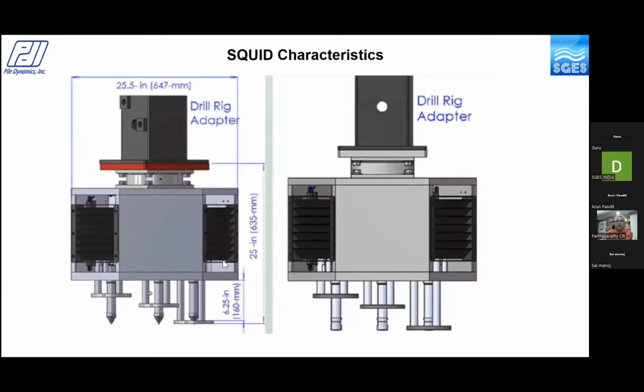Okay, so SQUID is a shaft quantitative inspection device. This estimates the thickness of contamination in the pile borehole, particularly useful for rock-socketed piles, which derive their capacity from the base. We do not want any polymer or bentonite to be accumulated at the pile base.